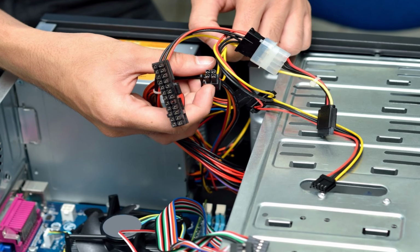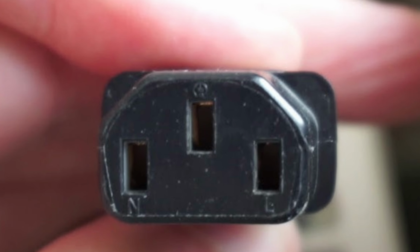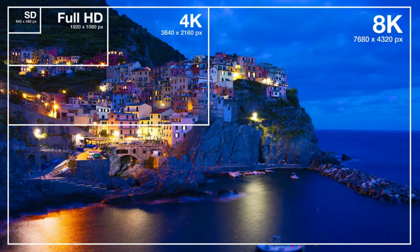Another reason you might be seeing no signal is power supply issues. Make sure the monitor is receiving power. If you suspect the power cord might be the problem, try swapping it out or plug it into a different outlet. Your screen resolution could also be causing the problem.